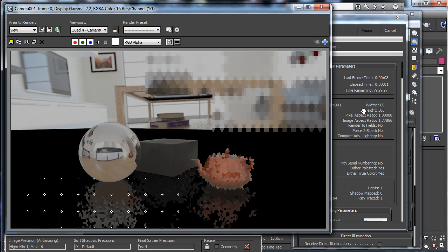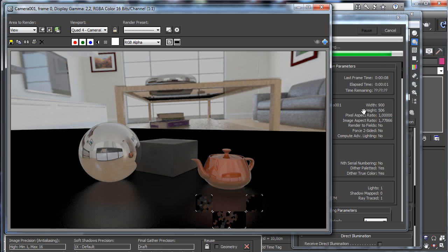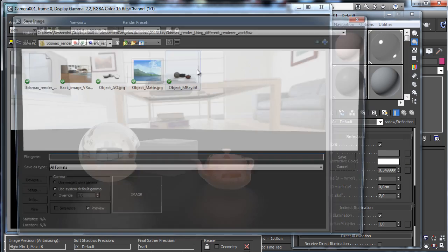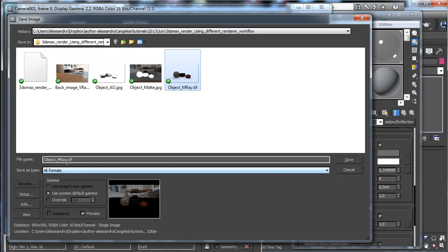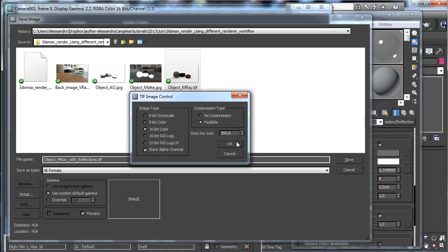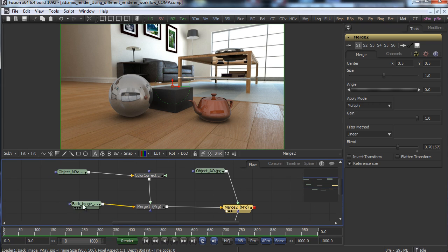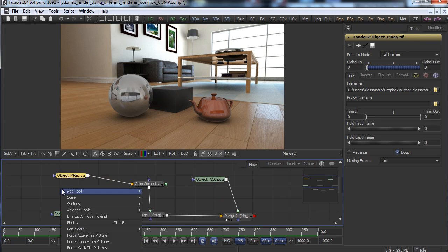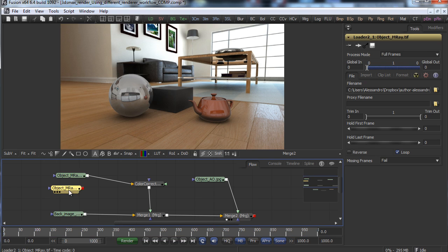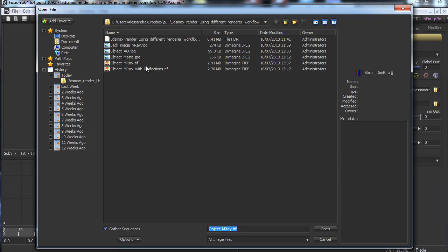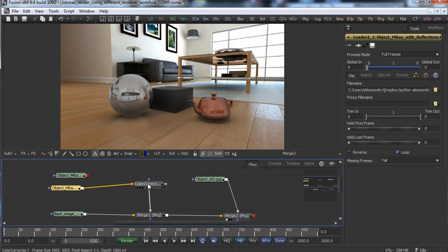Then we'll see, for example, how to add a really simple thing done with the film effects, just to see that using other rendering engine can follow the same way. So let's say that now we have VRay, let's say with reflection. Okay, save. Let's go back there, and let's try to use the other one. So we'll use a node, let's say Ctrl+C, Ctrl+V, and this one is the other one, so it's with a reflection. Let's connect there. Okay, and you see that we have the reflectivity.